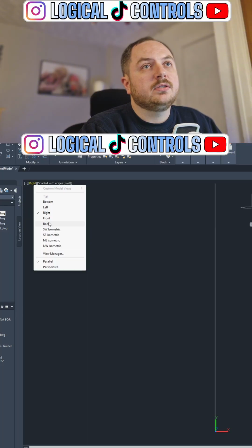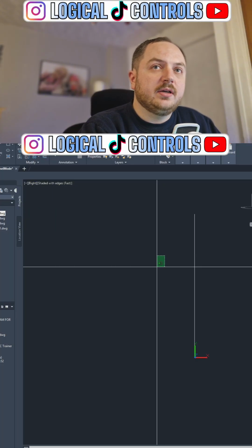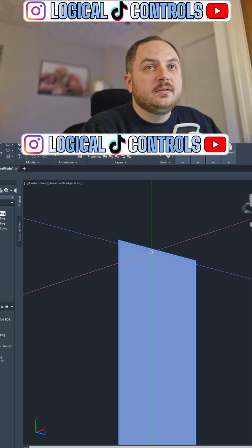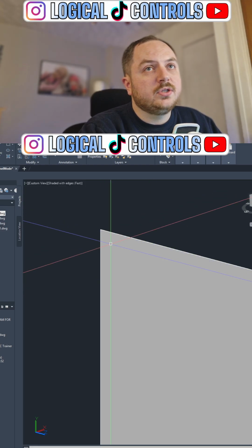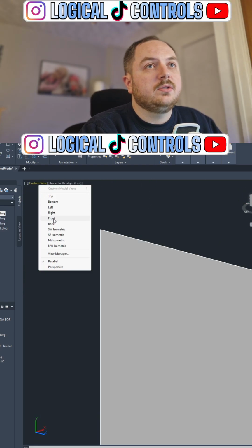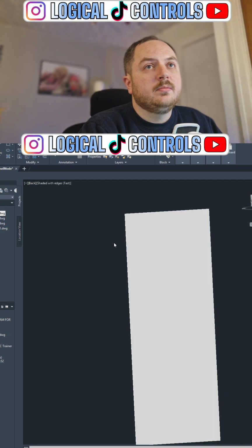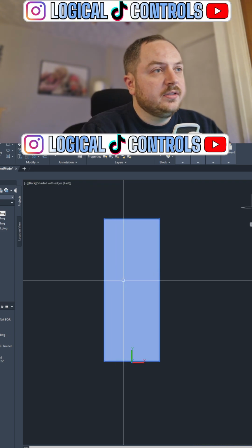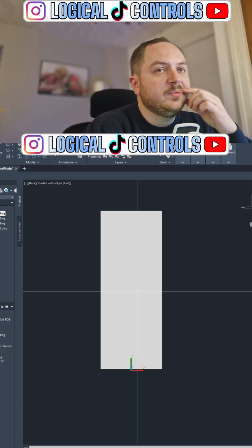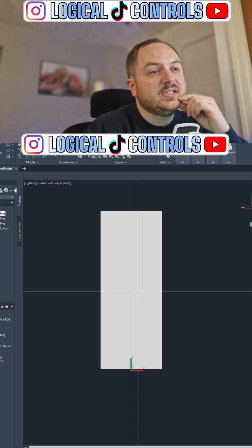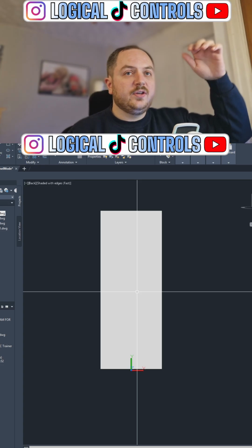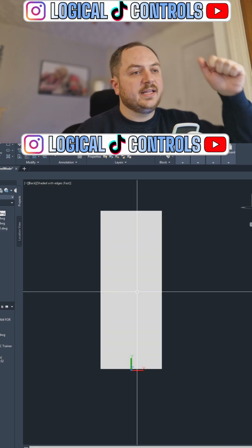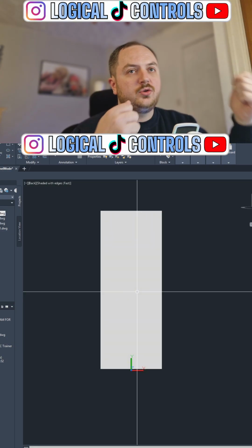Don't want the right hand side. And actually as well, in reality, this mounting plate would have return folds on it, so I will show them as well. Because the length for this piece of metal, it's only 1.5 mm galvanized steel, and if you had no return folds on any of that, it would just bend and twist and all sorts.